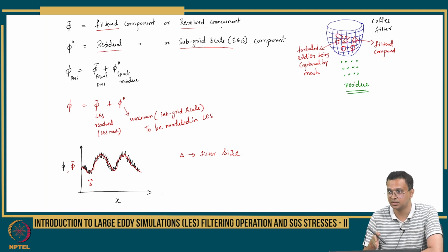So in LES, the user has a bigger dependency on choosing the mesh and deciding how much is to be captured, right? In principle, you must capture all the large eddies except the dissipative eddies. If you don't, then your model is not capable of giving good results, because what you are modeling is only the dissipative eddies. Their role is very clear.